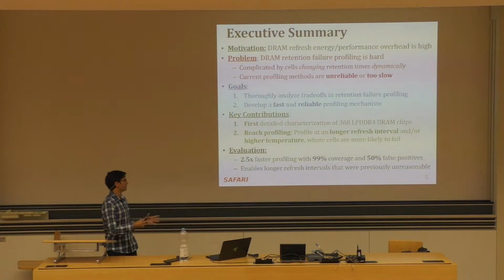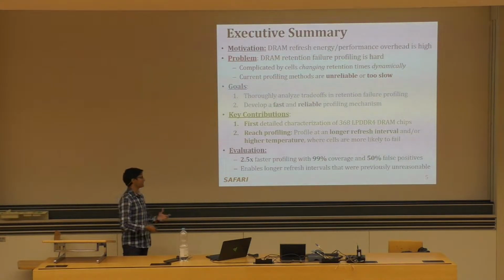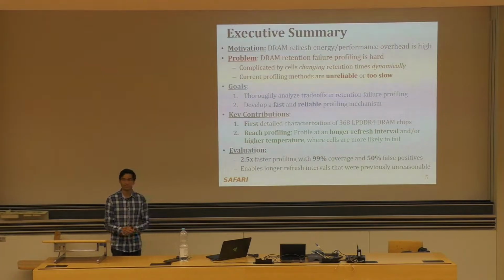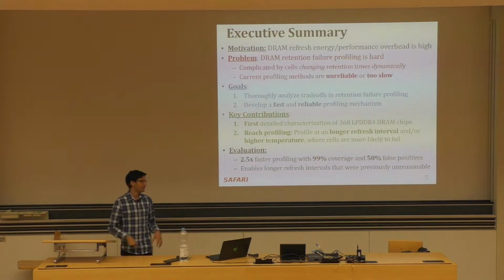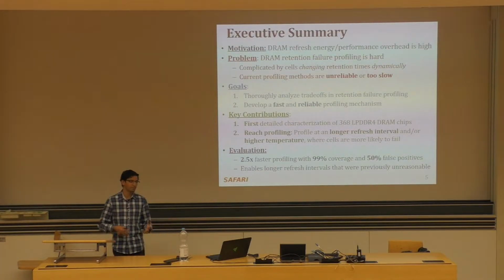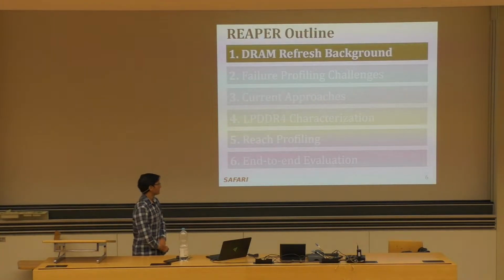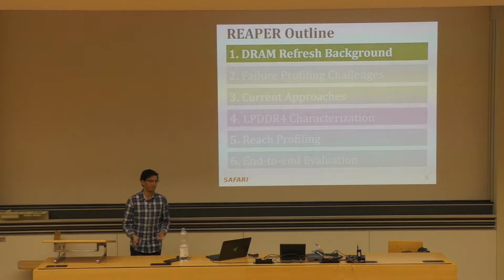Through our evaluations, we find that reach profiling gives us a significant performance and reliability improvement over prior works, and it actually enables longer refresh intervals that were previously unreasonable due to profiling overhead. Okay. So I'm going to start off with some background on DRAM refresh, right?